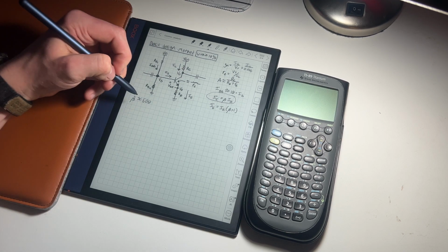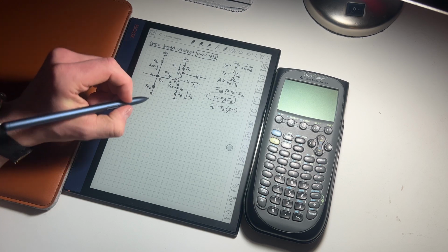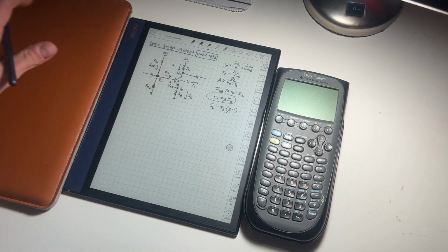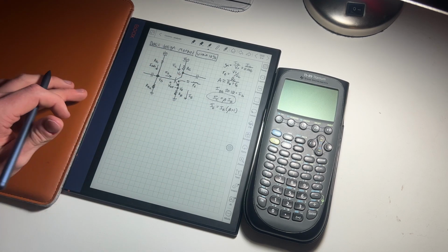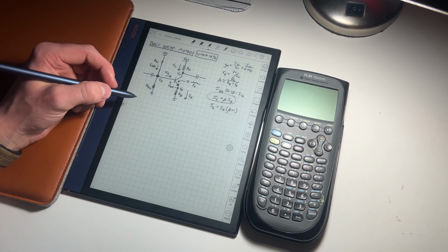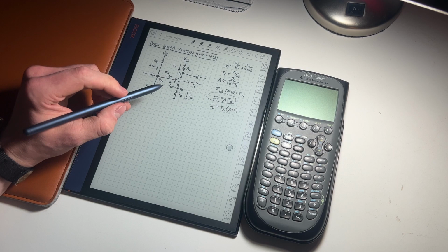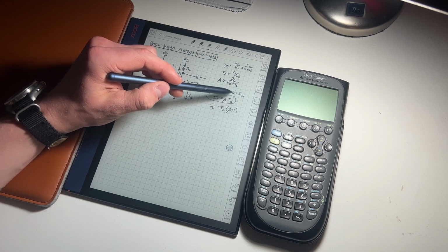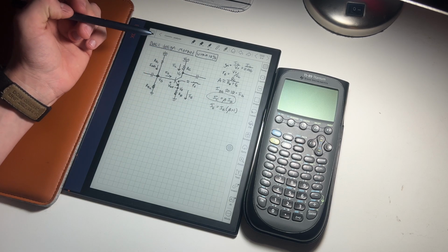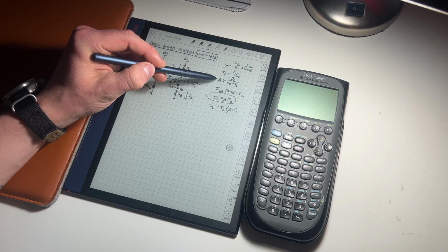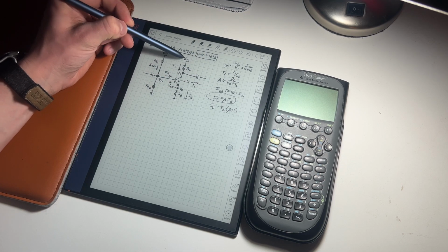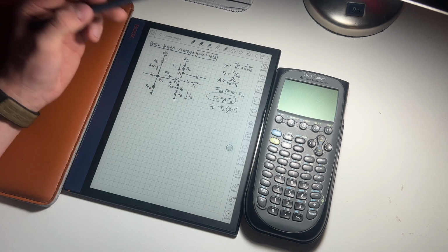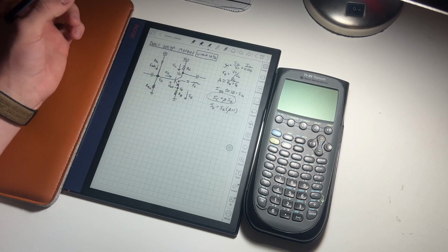However, one thing you have to note is that beta, even across transistors made on the same day, on the same chip, with all the same components and machinery, the beta will vary. It will always vary. So it's actually bad practice to design an amplifier solely based on the beta of the transistor. Now, because we're setting our gain relative to the collector resistor and the emitter resistor, we actually don't rely as much, or at all really, on the beta of the transistor.